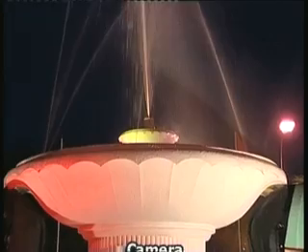And the attachment steps can be double layer interaction, van der Waals forces, adsorption and interparticle bridging. We can say that, mechanism-wise, rapid sand filtration and coagulation are almost the same. One is a static system and another one is a dynamic system. So it is always advisable to have coagulant in the rapid sand filter.